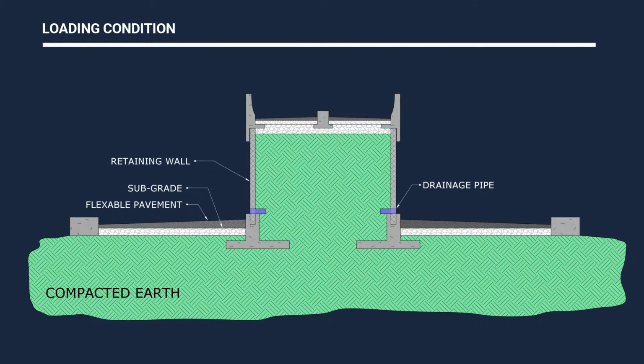This is a cross-section of the BMC flyover. In this type of construction, the load is transferred by compacting layers of soil to the desired height of the flyover, and retaining walls are constructed on the sides to retain the soil pressure and its position. So, the soil has to be properly compacted and dense before applying load on it. It looks safe enough, so let us allow the traffic to flow over the flyover.